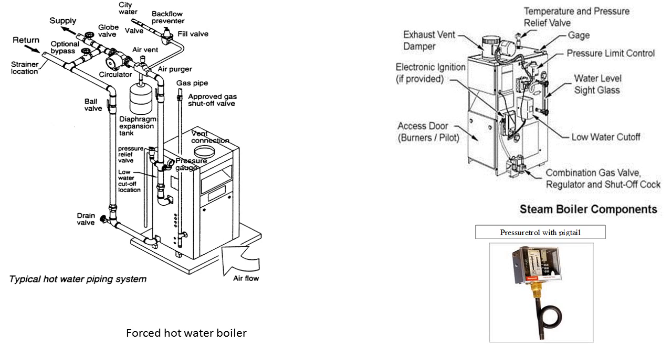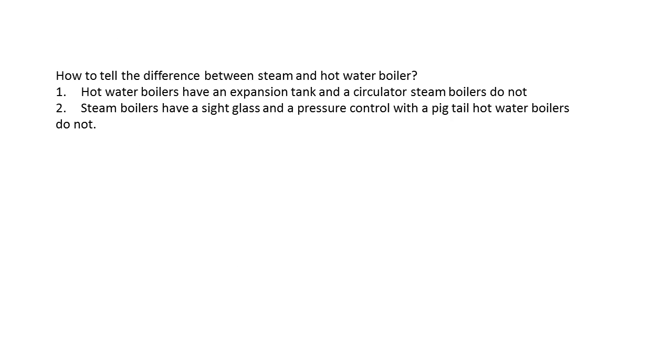Also on a steam system, you will find a pressure limit control with a pigtail. It's a very distinctive item. A forced hot water system will not have that control.